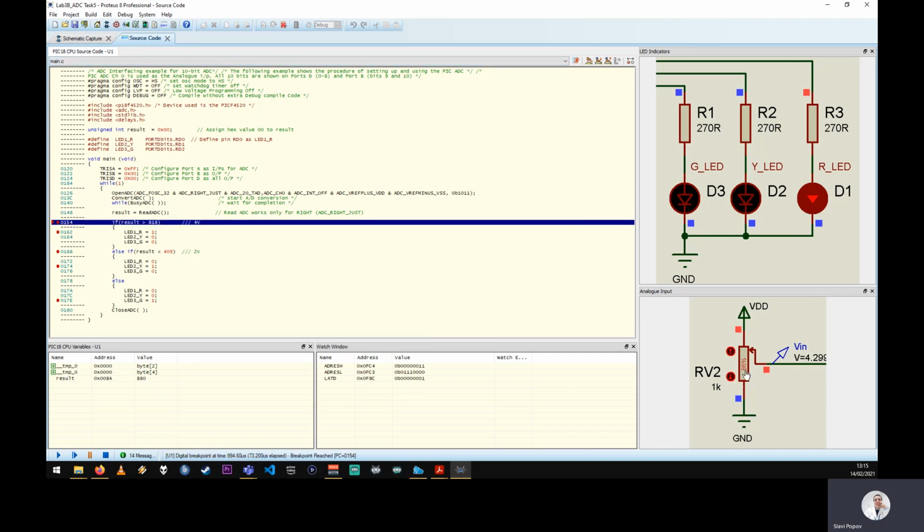And now we're gonna try and switch it back to 50%, which is 2.5 volt. That's within the range. We're gonna keep checking, and you see as the simulation progresses, the voltage drops, and it displays green LED at 3.6. So that's correct. It will detect as soon as you're within the range. It will detect that, and it will turn the green LED on.